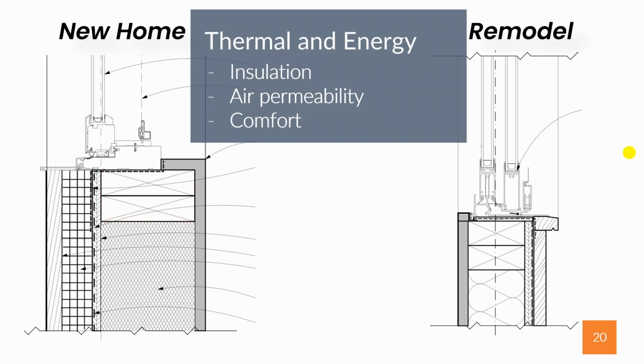So the R value of that wall and the performance of it with a continuous insulation barrier cuts way down on thermal bridging, much more energy efficient and comfortable inside. It also reduces the possibility for moisture to condense along thermal bridges and rot the wall out from inside. This is a remodel. We're showing on this one, we insulated the walls because we opened the wall.